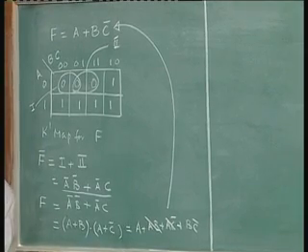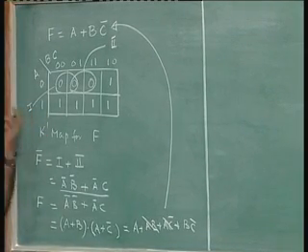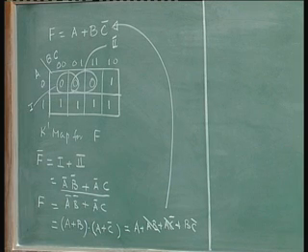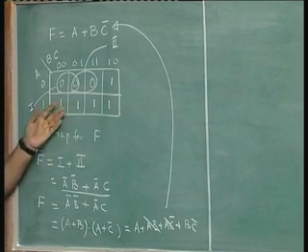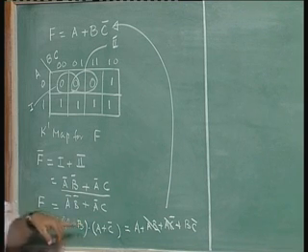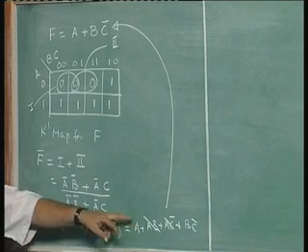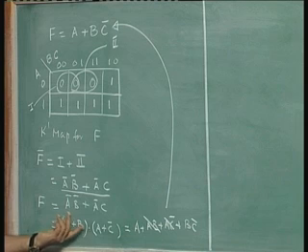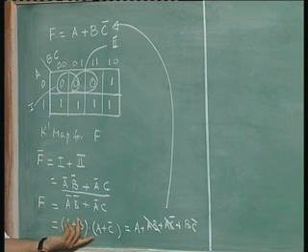The point I am trying to make is, a couple of points really. One is a smaller number of ones, grouping is easier only if they are randomly situated actually. When ones are nicely grouped, you may find a good simplified expression, minimum form. But if you had ones and zeros spread in a random fashion, and more zeros than ones, or more ones than zeros, maybe it is a good idea to go for a simplification using zeros. The second thing is, this is the expression for f without this simplification. This simplification I did to prove that this is same as this. I can stop here. This is the minimum product of sum form.